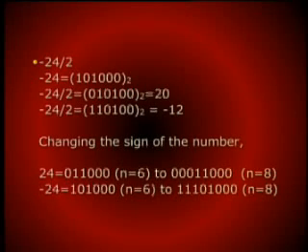Therefore, when we shift right and we see that the sign is changed, we had the sign bit as 1, that should be copied as 1 and not as a 0. This is the familiar problem of sign extension which we have discussed earlier in our processor implementation. So copying the sign bit would now give us 1, 1, 0, 1, 0, 0, which is minus 12 decimal.